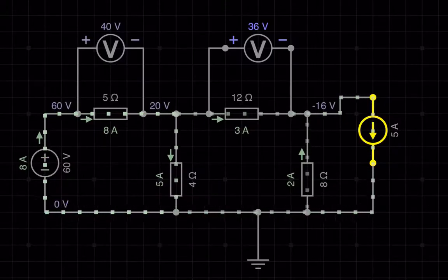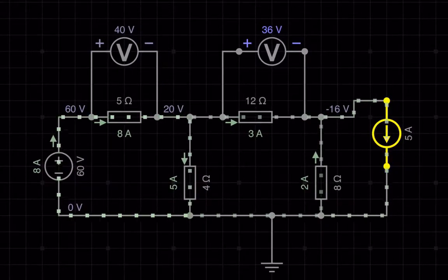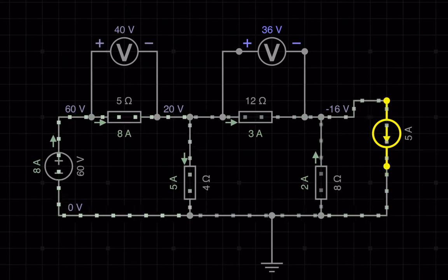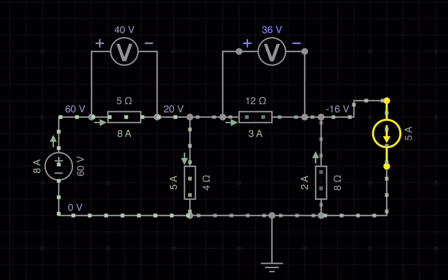So remember that there's more pressure acting over here on this part of the circuit, moving along. And then this will go here. Again, remember you got 3 amps coming over here to this node. You have 2 amps coming over here. 3 plus 2 gives you 5 amps, and that's what you have over here. Also, I did the simulation here, and you can see that our results are pretty consistent with what we got here also.